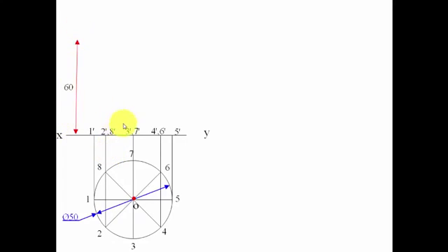So this is going to be 60. We need to go ahead, up ahead 60 millimeters. So this is going to be the axis, and now let us say that this point over here is the front view of the apex, that is O dash. Now let's join all these points with this apex. It should look something like this.